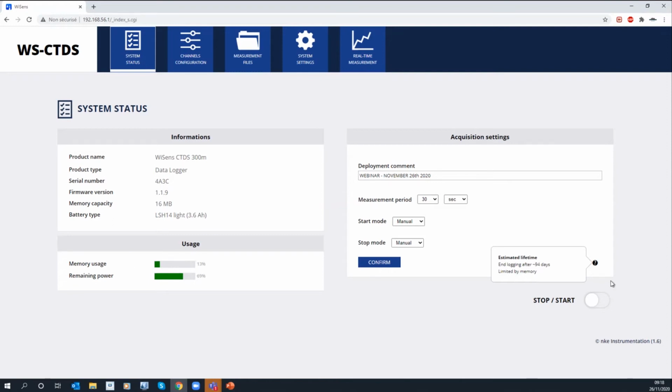So this is very interesting, because if you program to recover the data logger after a longer time, you have to find a solution. That means you can reduce the frequency to have less data inside your data logger, or change the start condition. In some cases it's not necessary to do the measurement all the time, but just between some conditions.